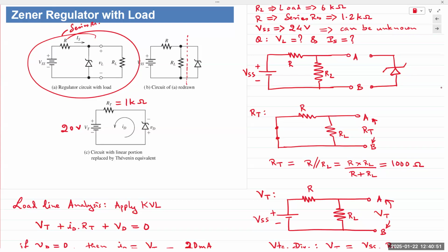If the supply voltage increases, the Zener diode must regulate so that the output voltage across the load resistor remains constant. If the output voltage remains constant on RL, that means the current through RL must also remain constant, or at least within some small variation. So if Vs increases, the Is current coming from there increases.